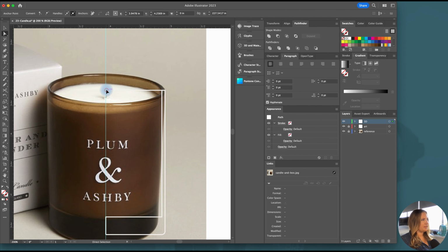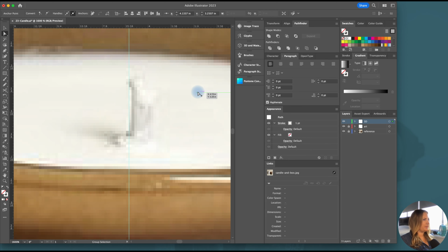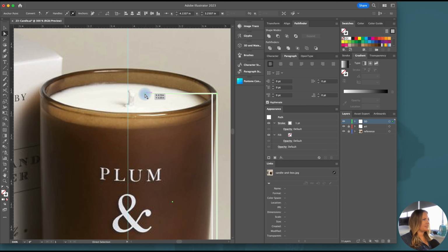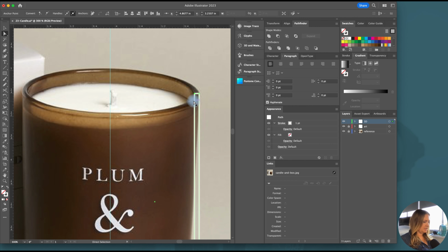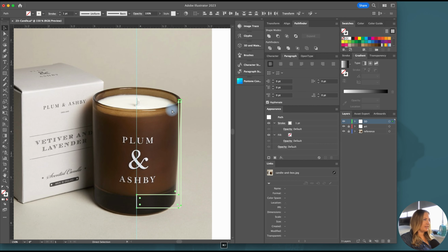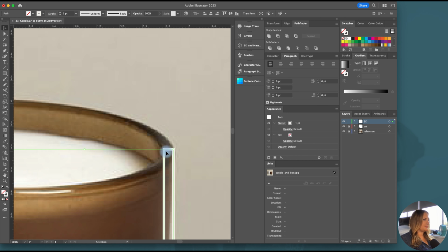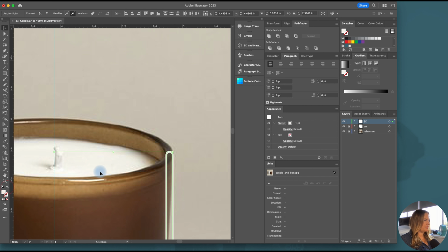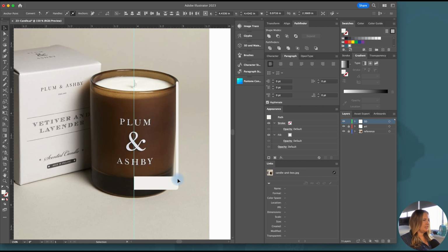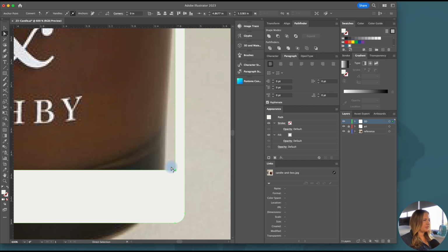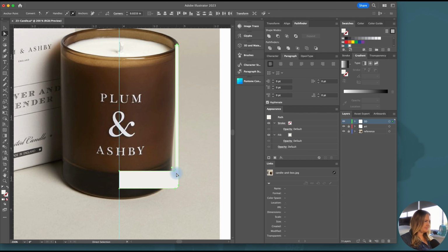And then this anchor point that's over there, I'm going to drag to meet up with the edge here. Selecting both my paths and then hitting Command J will unify that together. And now that allows me to select these two points and treat them like it's all one shape, curving that in. And then I also will add a little bit of a curve inside here.